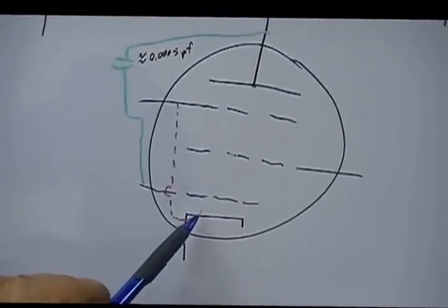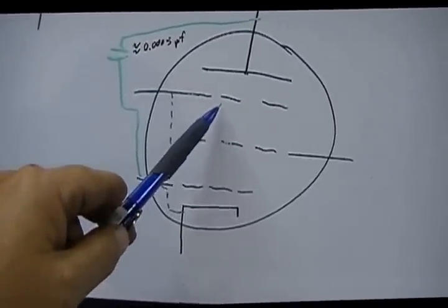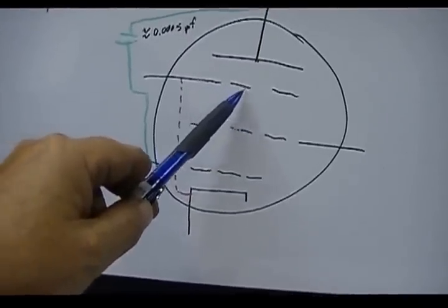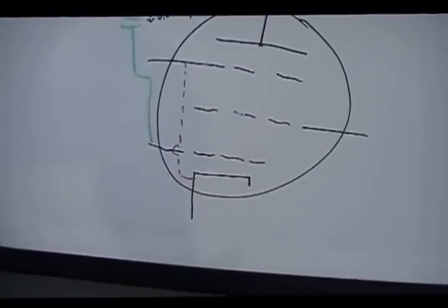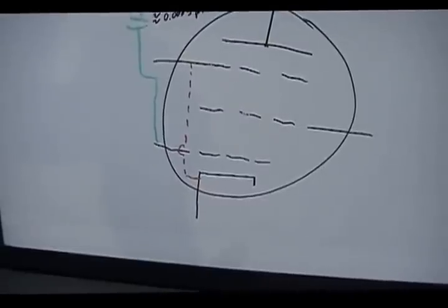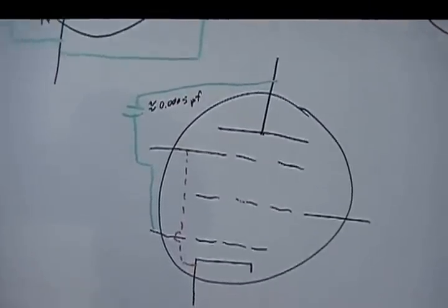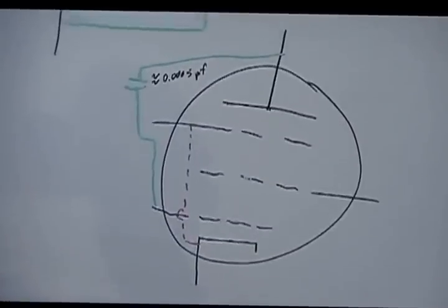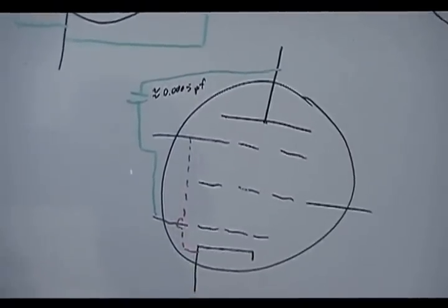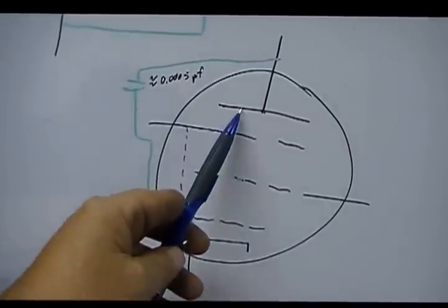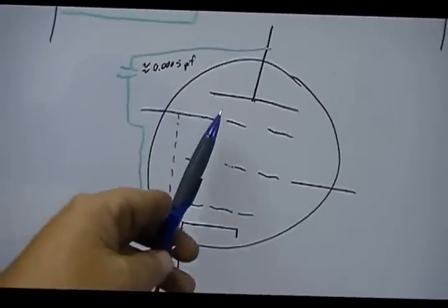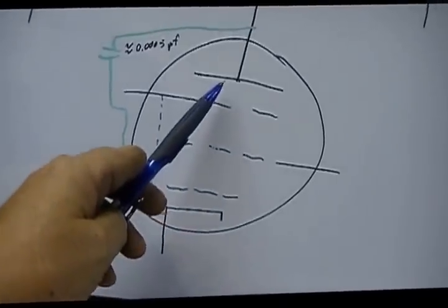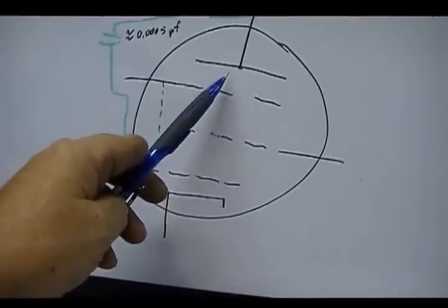Again, the electrons are moving faster and faster as they go through, and when they get up here, it's another screen, it's another grid, coil wire, and they make it pass without any problems, but it does slow them down a little bit. The ones that get fairly close will get really slowed down, where when they get to the plate, everything's perfectly fine. The ones that are out in the middle between the wires are still going pretty fast. So what? They knock off some electrons.